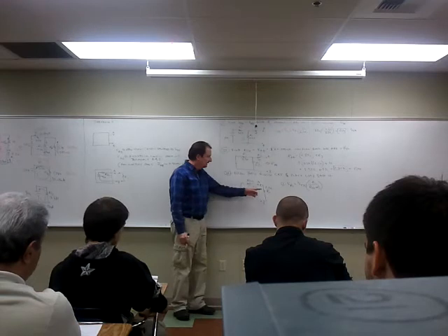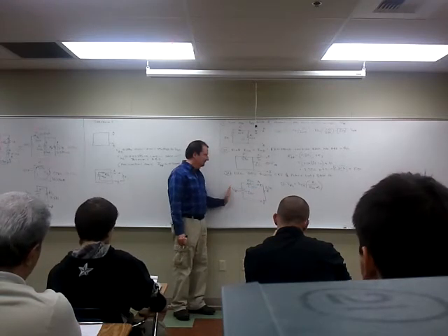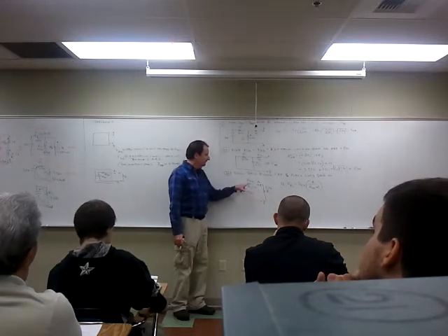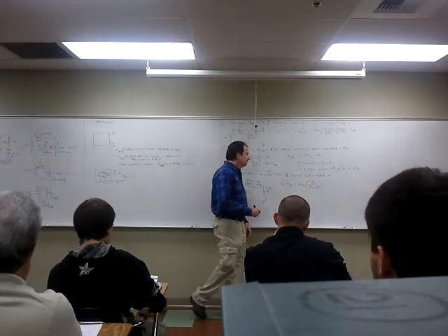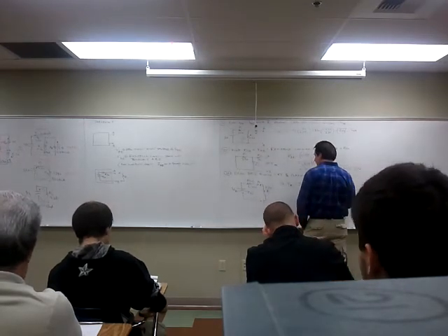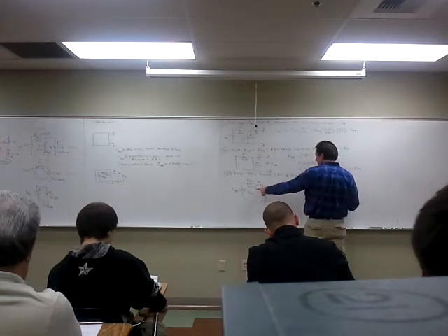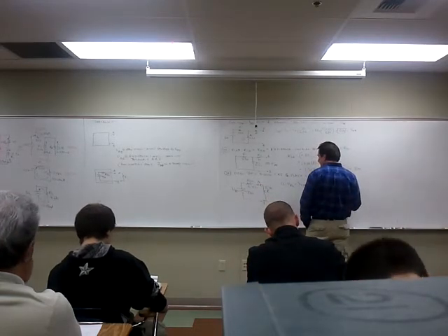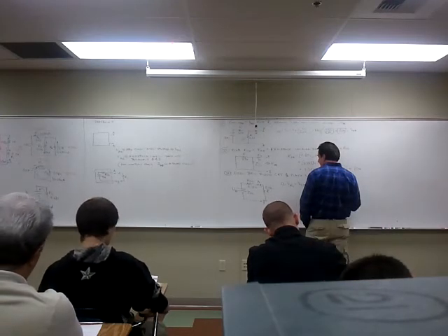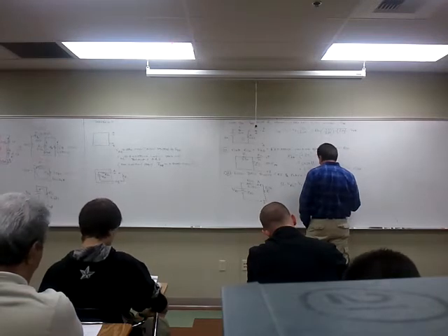Of course. But this R over the sum of the R's is the ratio times this voltage source. That's the voltage divider equation: the resistor we're looking at over the sum of the resistors times the total. So that's 20 volts times 2.7K, which is RL, over 2.7K plus 2.32K, which is 5.02K. Is that right? Yeah, that's good.